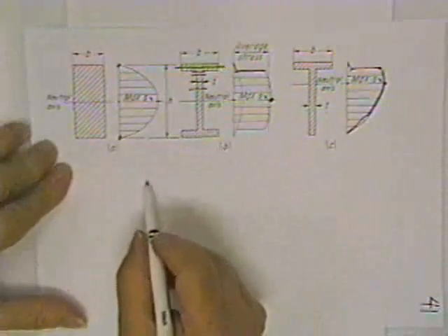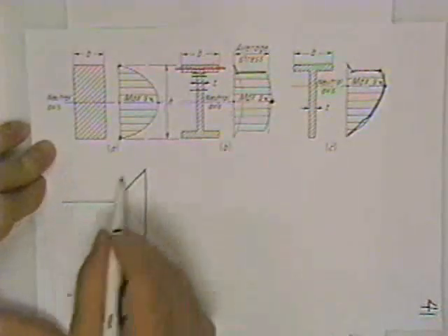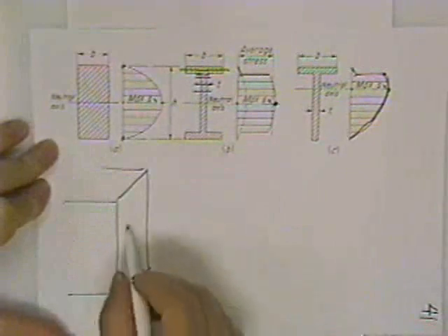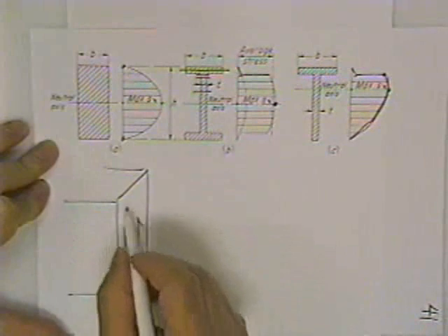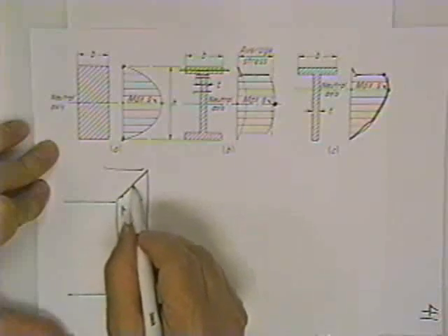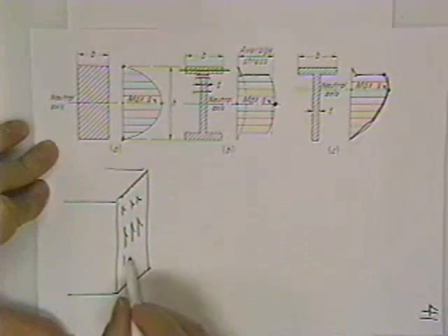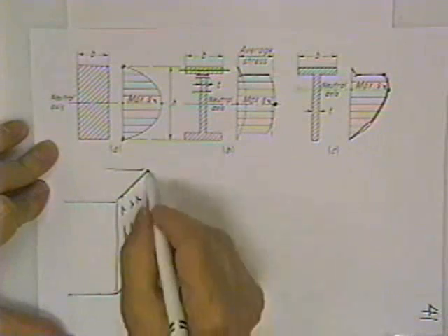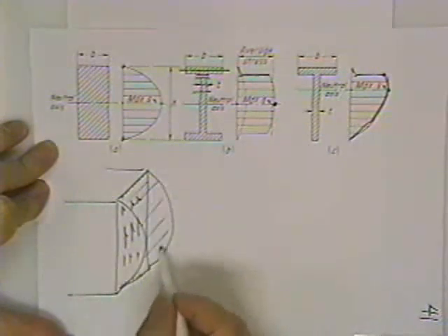If I could show you those, here would be this rectangular beam right here. You'd see great big shearing stresses at the neutral axis. You'd see pretty good shearing stresses a quarter of the way. You'd see no shearing stresses at all at the top. And then again, some medium-sized ones down here and some little tiny ones at the bottom. They'll be distributed parabolically, like that.